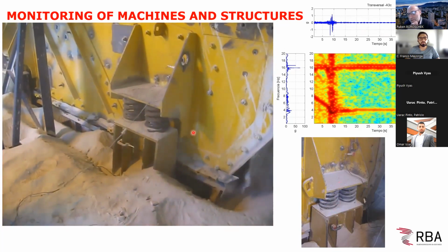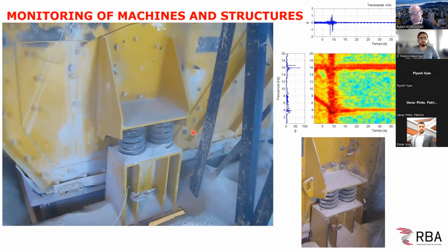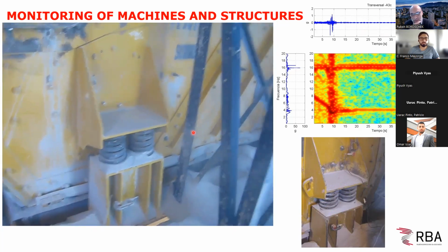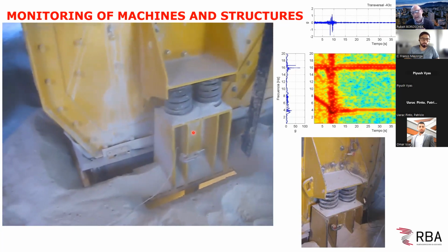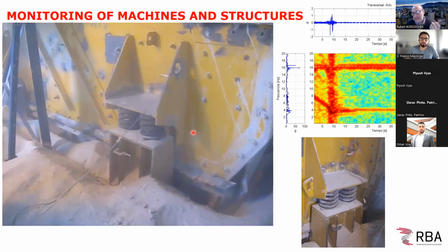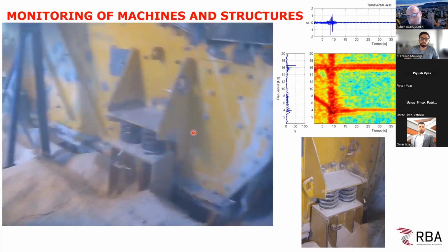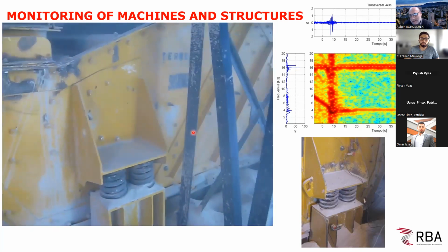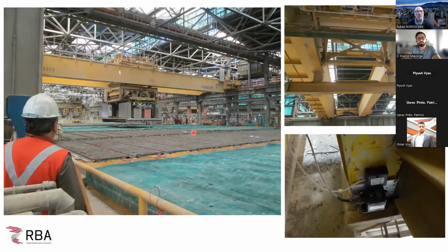And we estimate operational loads for fatigue analysis of the structure, and extreme operational loads for maximum stress evaluation, and then you add the seismic and the wind and the snow in order to do the modeling of this type of structure. So again, it's very simple, non-parametric things, but with the appropriate sensors to capture the loads that we need. In this case, the dynamic transfer load and the damping of the system for the analysis.